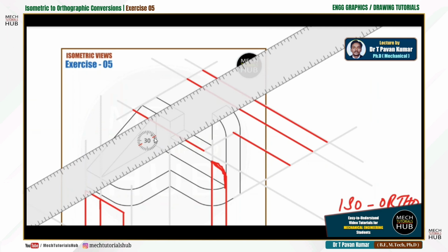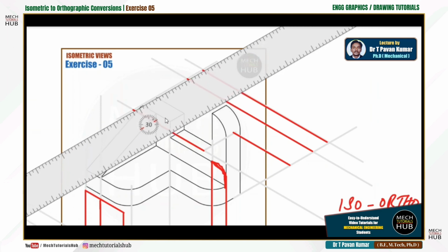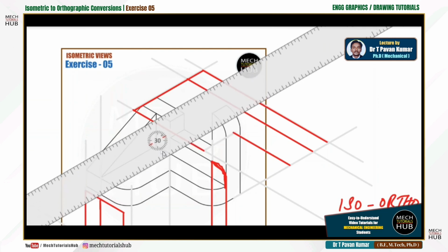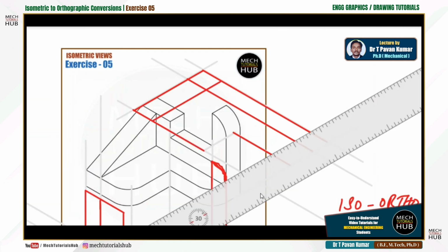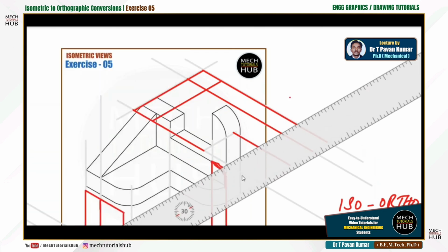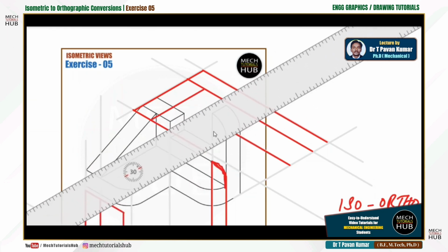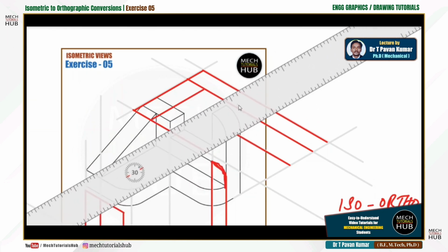Now try to understand the logic here. Whenever we are dealing with the top view, we are drawing only horizontals and lines at 30 degrees inclination, whereas when you deal with the front view, you deal with 30 and 90 degrees. And for this thickness, let me drop the line something like this, not like this, not till the end. This line is till that point only, till it touches. Alright, other than this there is an extension of 10. That 10 I just drop it down here.